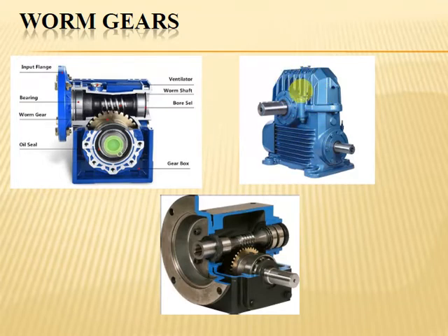As we are discussing, we have a heat generation issue in the worm gearbox. So how to dissipate the heat is the issue, and for that fins can be provided. This is one of the important aspects while designing an industrial worm gearbox. Practically speaking, a worm gearbox needs a huge number of fins, as there is a sliding velocity or rubbing velocity.